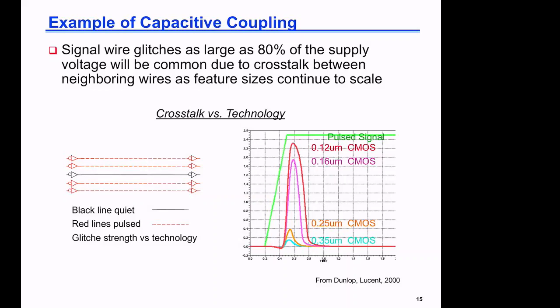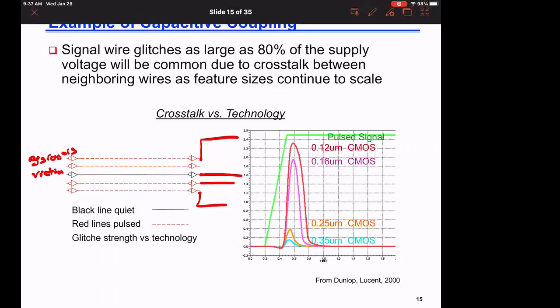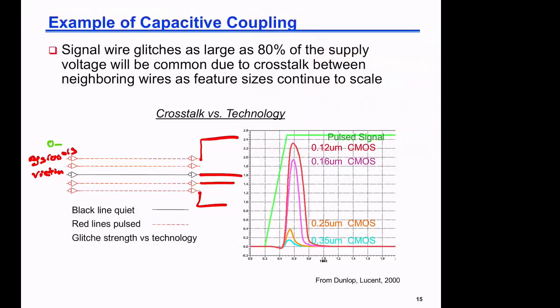If we have, for example, wires going everywhere to different locations feeding signals. The signal in the middle is my victim signal, we call it, and the red ones are the aggressors, and we will talk about them later in the course. And this is the victim. And let us say that here all of these signals have as input 0, and this also has as input 1.